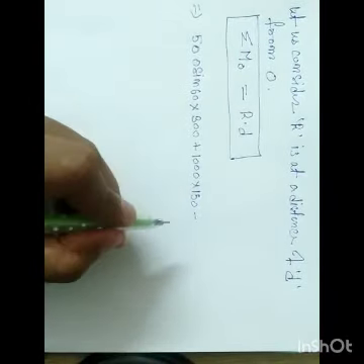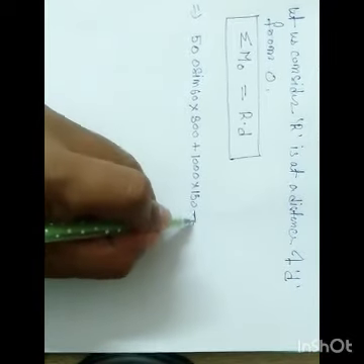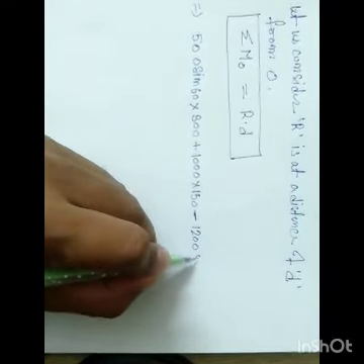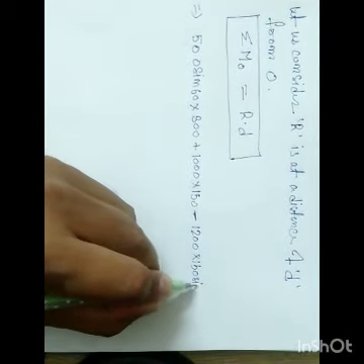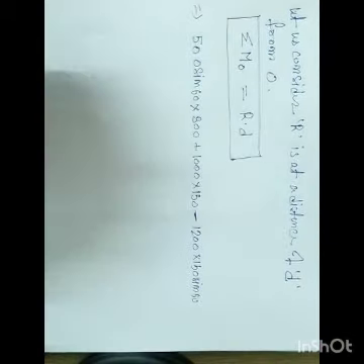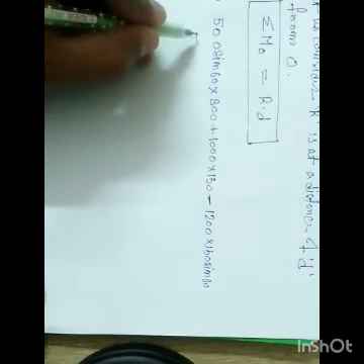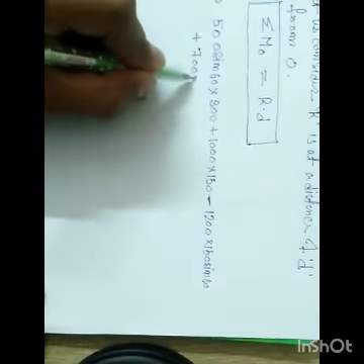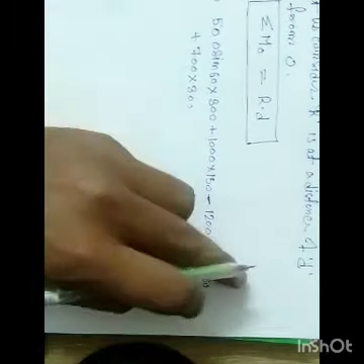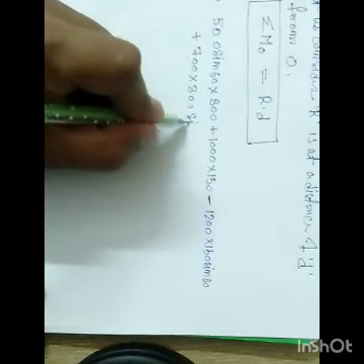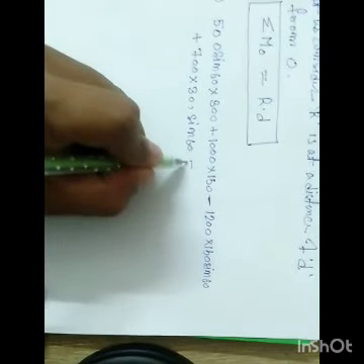So it is minus 1200 into 150 sin 60, right? One more force is there, plus 700 into 300. This whole length is 150 plus 150, 300, and its vertical component is sin 60.